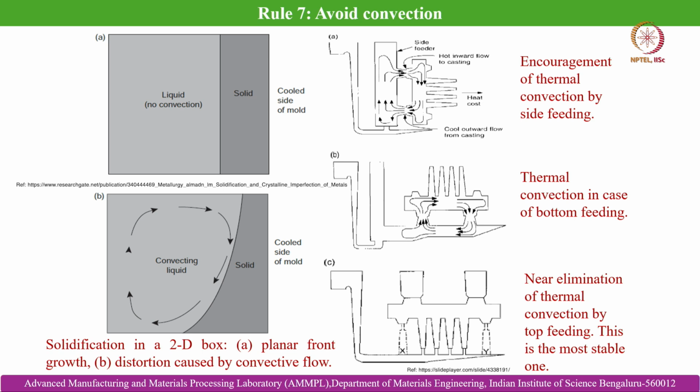It is more related to the flow physics that we observe within the mold cavity, which can be effectively dealt with by effective design of the riser, ingate, and also the runner dimension. We will of course discuss within this module itself, in subsequent classes, how we can design a mold cavity effectively so that we can achieve proper flow physics within the mold cavity, so that in turn we can get desired mechanical properties in the solidified object.